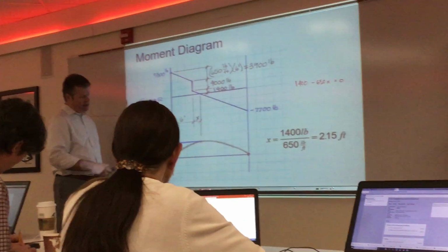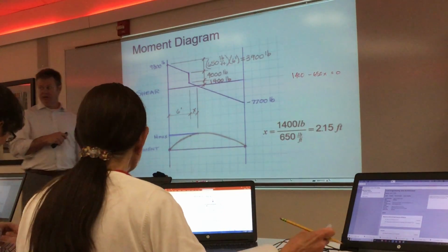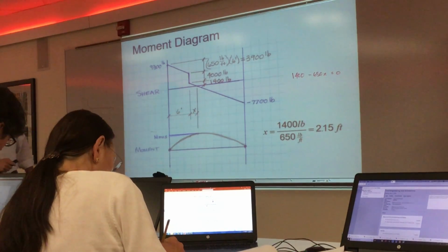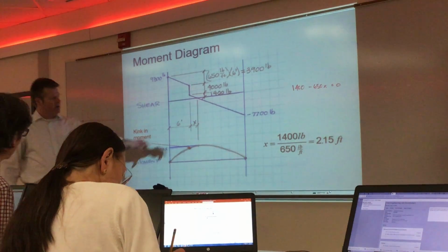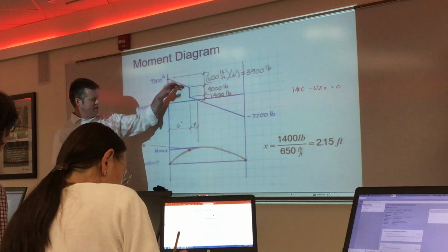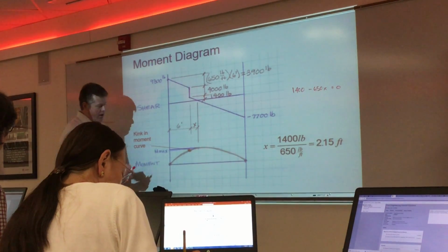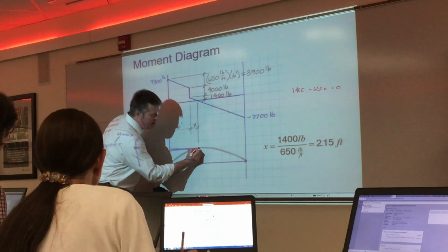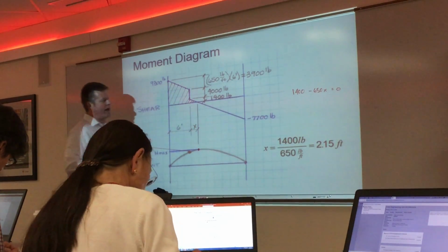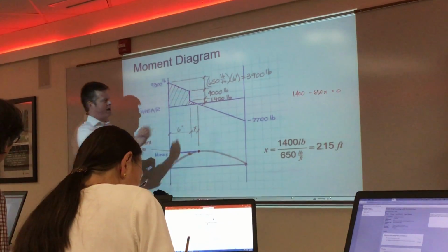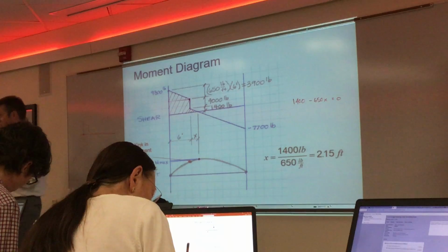This point is equal to the area underneath the shear diagram. I think they're actually going to highlight it in a second. It does kink, because this happens, so you changed your magnitude abruptly there. But the magnitude of this point is equal to this area. That's how they do it in the curriculum: they take the area and break it piecewise into a triangle, a rectangle, and another triangle. That's fine.